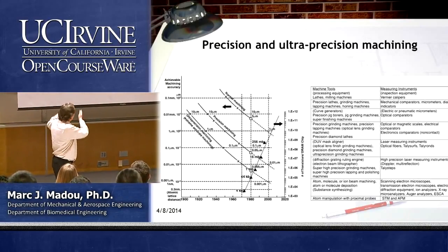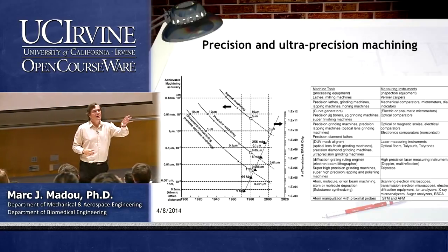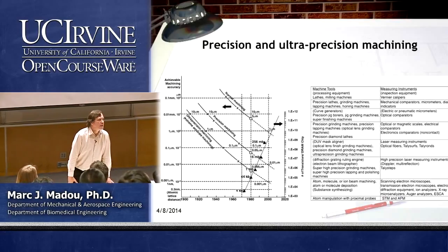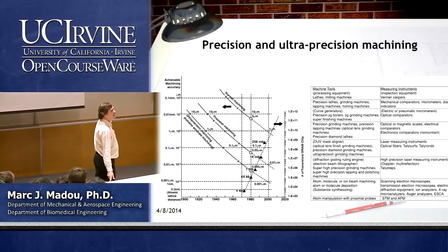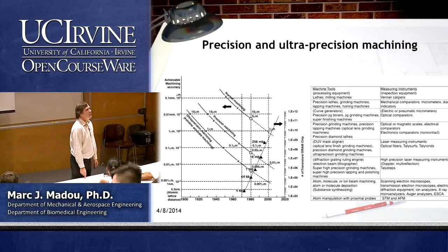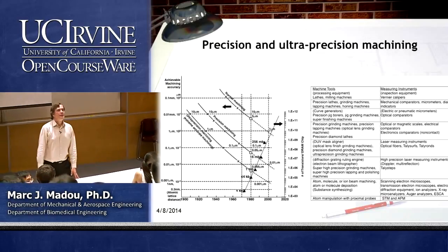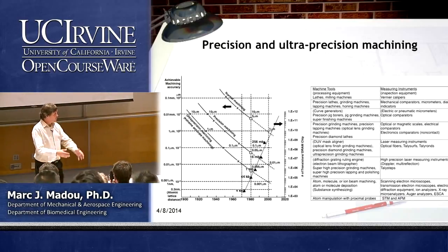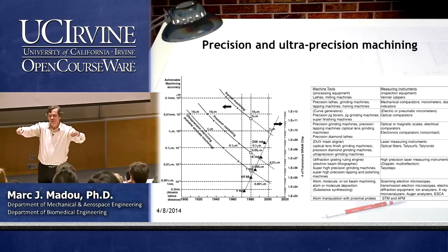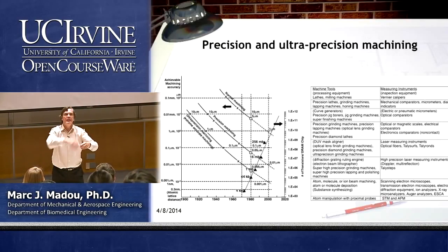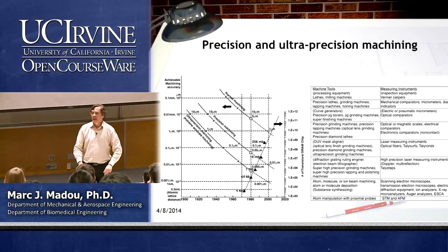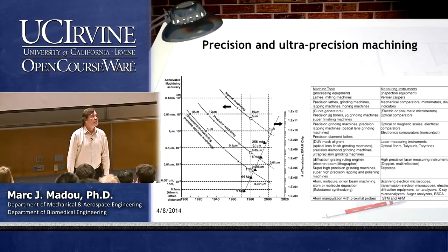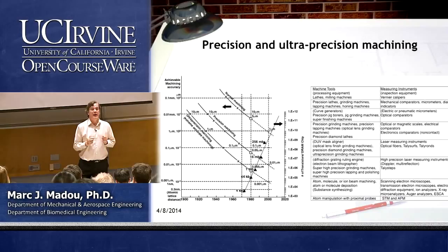What determines the fact that both these developments in mechanical machining and in integrated circuits were developing this way? What's controlling the progress? Packaging between the IC circuitry that's fabricated with lithography and the packaging itself, which is micromachining. More accurate position stages. Exactly. It's the position stages, isn't it? You remember now, right? And actually, I kind of highlighted it by saying, look, in the beginning, 1977, it was kind of like a poor XY position stage, right? There was no feedback. They kept on improving that and improving it. They made it vibration-free. And they got improvement both in mechanical machining and in electronic lithography, right? So the key binding this is how good an XY position stage you can make.